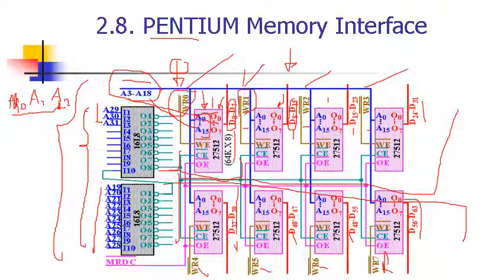Okay, while if you are trying to read data, you need only a single memory read control, which goes to all chip selects, to all 8 banks. So all 8 banks will be opened up for you, and all 64 bits will be loaded to your data bus. If you are interested only in the least significant 8 bits, you take them from bank number 0. The least 16, you take them from bank number 0 and bank number 1, and so on.